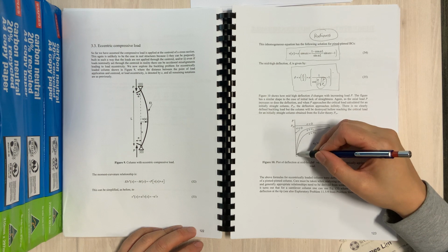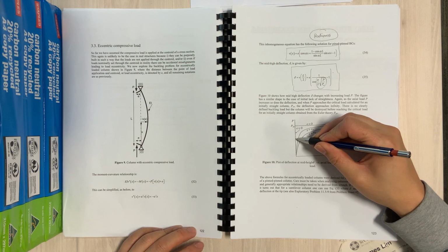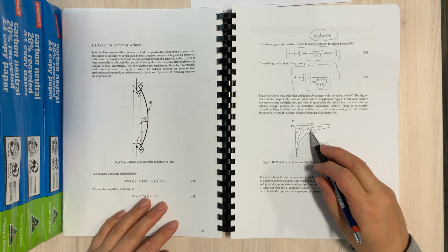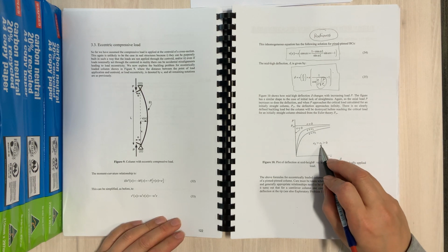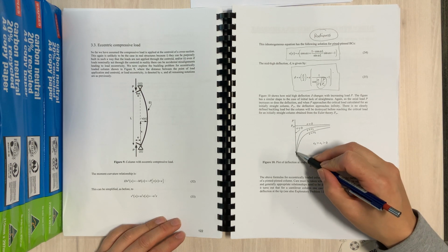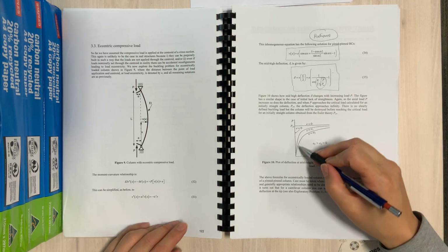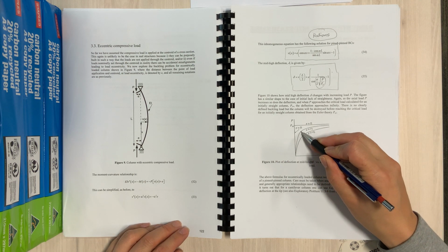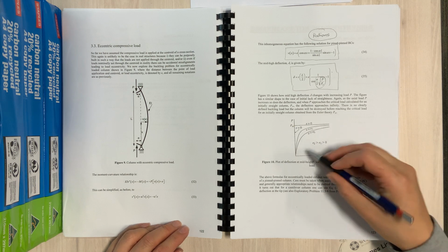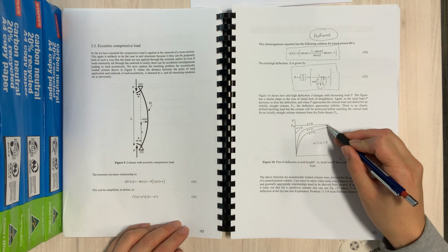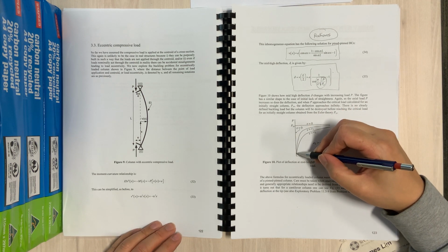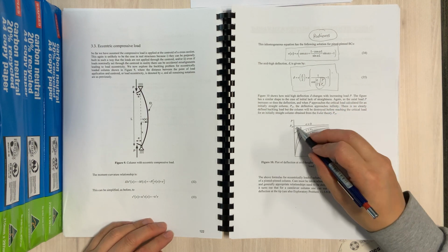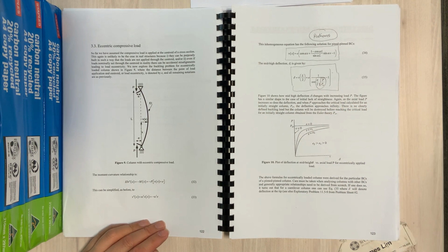Of course there will be axial shortening, but it would go up almost along the axis here, and then it would shoot off. Now if your eccentricity is equal to E1, where E1 is less than E2, we're just showing some values of E there, the graph, instead of going up and then sudden failure, shows a more gradual failure, a failure that can be expected, as you can see the load going up and then going down from there. So when E is 0, it's very, very sharp. It's suddenly at the point where it's reached PCR, pi squared EI over L squared, and everything suddenly shoots up to infinity.